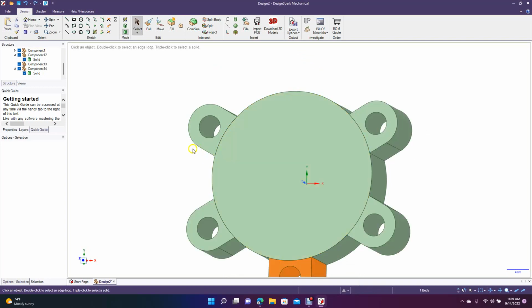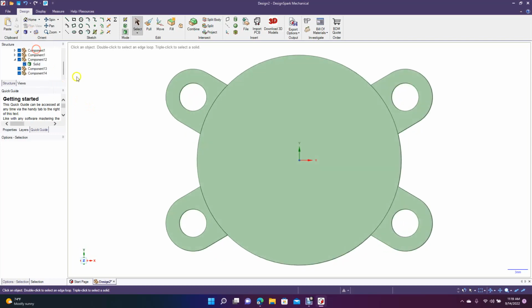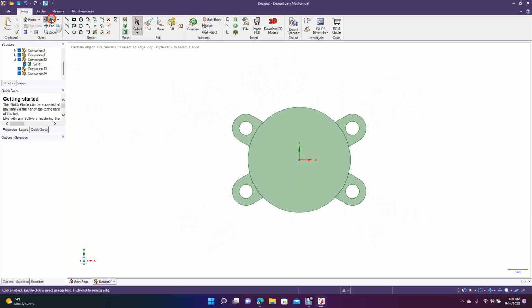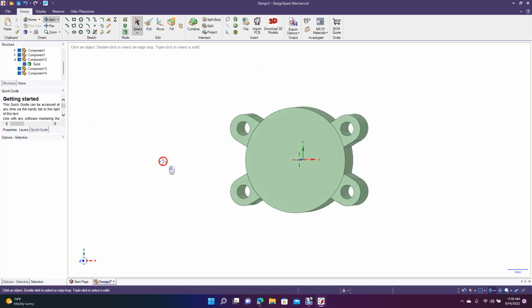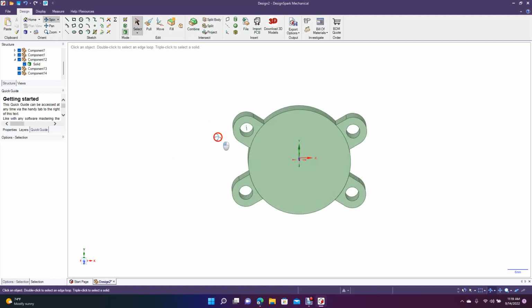Multiple clicks, right mouse click, make independent, delete. Oh, undo. Multiple clicks. Okay, it is independent. Delete. Okay, so now we'll go back to top. Okay, so now you have a piece like this. So you can do that on any pattern that you make. As long as you multiple clicks, select everything, and then the right mouse click and create independent, you're going to have a piece like this.